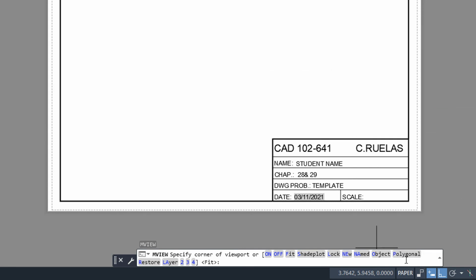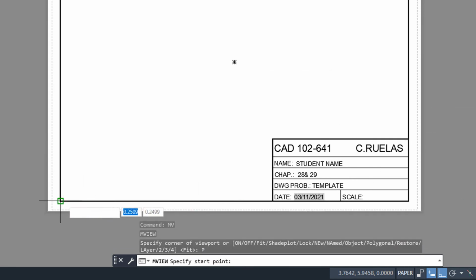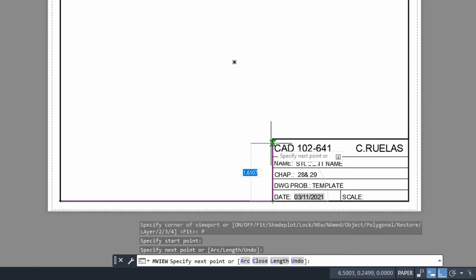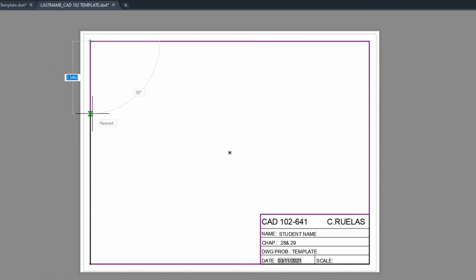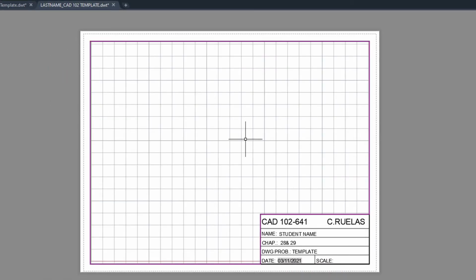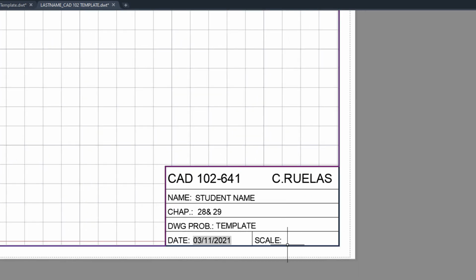We're just going to select Polyline or Polygon and draw an outline around. You can type in C to close. And now we have a viewport. Okay. Continue on with your field. We're going to go ahead and type in field again.